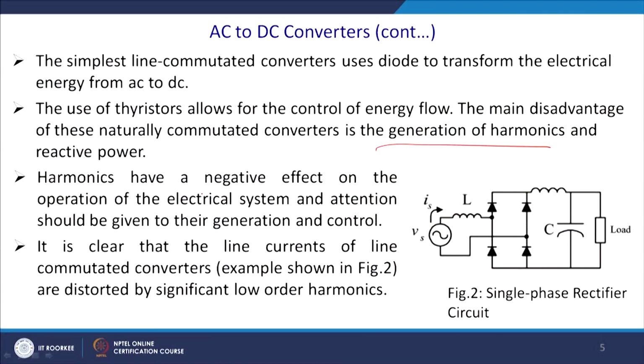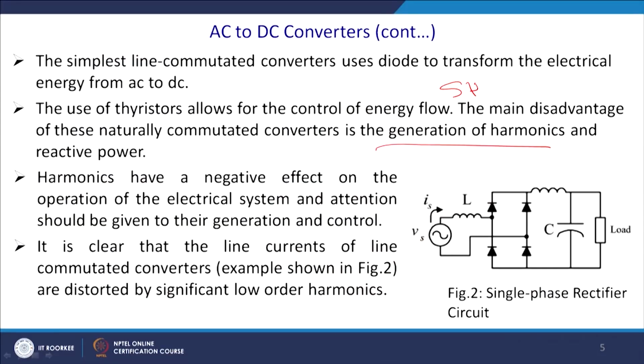Harmonics have a negative effect on the operation of the electrical system, and attention should be given to their generation and control. We can use a technique which we have already discussed in my previous lectures in advanced power electronics and control, that is SHE, selective harmonic elimination. You can look at that video lecture, and there you can see how this THD can be reduced.